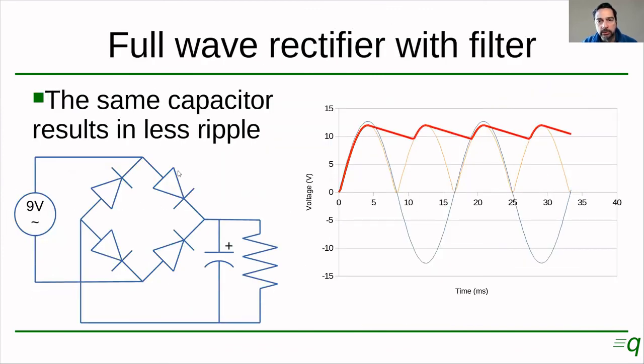This was a 9 volt source, and the voltage here is oscillating between pretty much 10 and 12 volts, right? So the peak voltage is about 12 volts, right? And if you were putting in a higher capacitor, it may be able to hold the voltage a lot closer to the 12 volts that you have here.